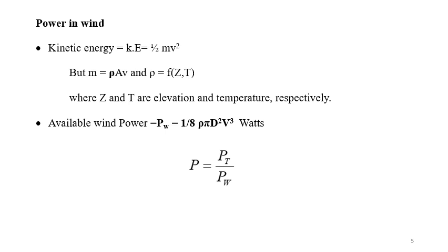So the equation tells us that power available is proportional to air density also. The density is always 1.225 kg per meter cube at sea level, and it may vary 10 to 15% during the year because of pressure and temperature change. So it changes negligibly with water content.